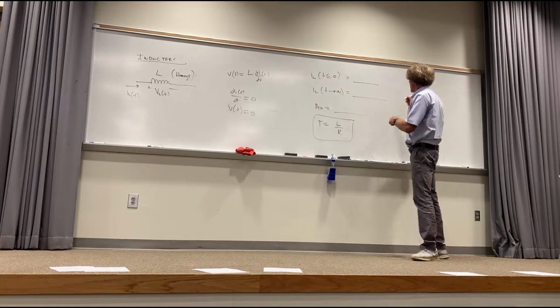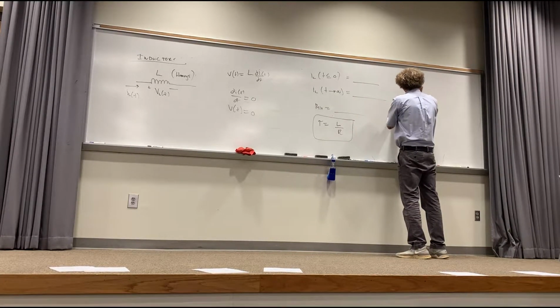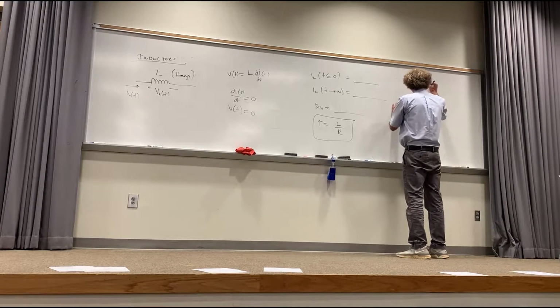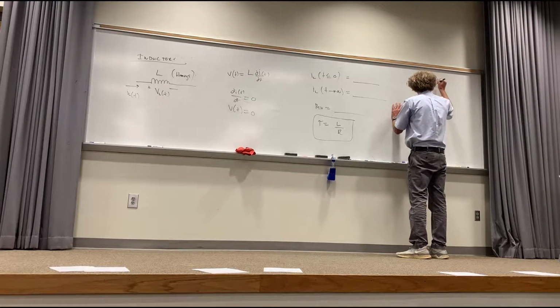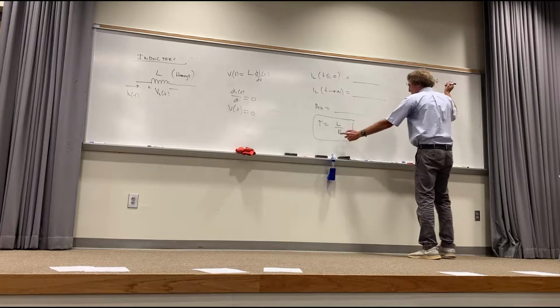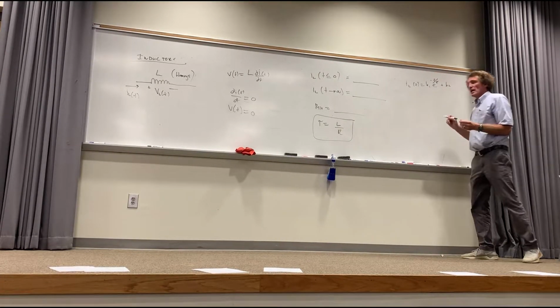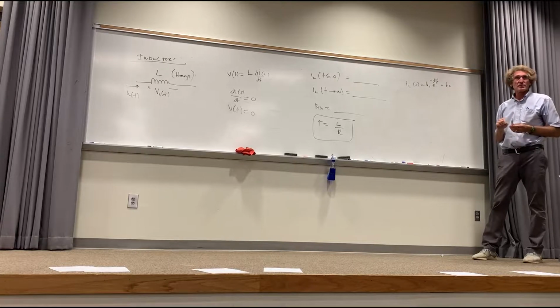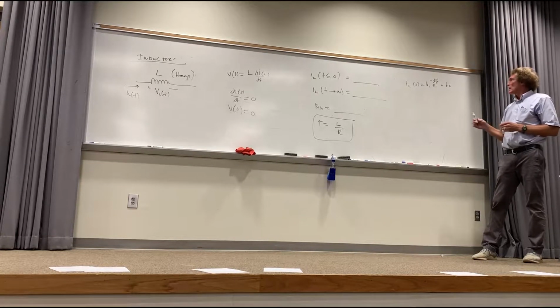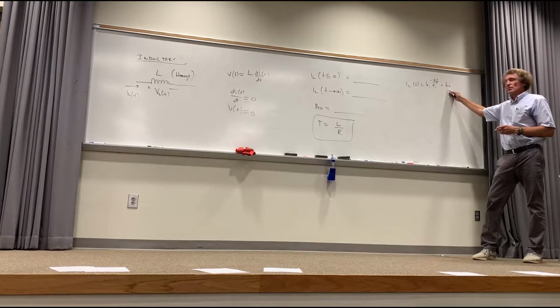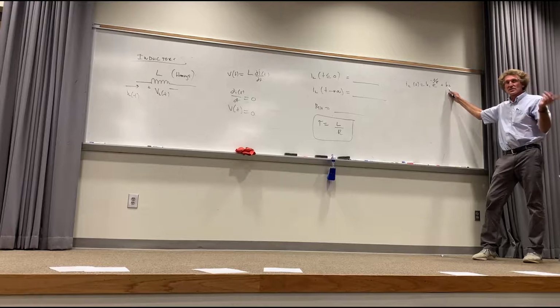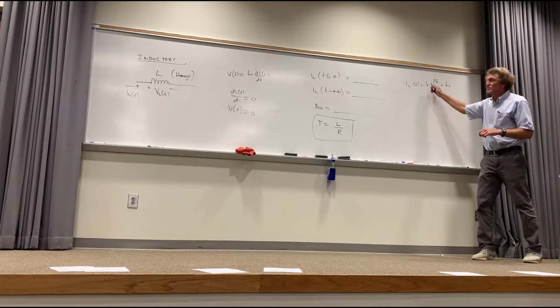And then you put this together: the current through the inductor as a function of t is K1 e to the minus t over tau, plus K2. Now, I'll make mention of this. I'm going to do some problems, but I want you to listen to me. This value of K2 is associated with the current flowing in the inductor as t goes to infinity. Can you all see this from the equation? Because as t goes to infinity, this term goes to 0.